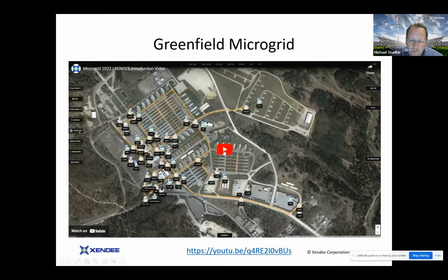This here is a real project that we did for a large campus. It's a very extended modeling approach here that we did with Xendee. It's a distributed microgrid. It has a lot of different nodes. And we had to connect all these different load pockets through cables, transformers, which we knew from the client. And then we were modeling at all these load pockets, different technology options. And the goal was actually really to figure out if we should have a more centralized PV system, or maybe the PV should go more on the roof, and how this will impact the transformers, the cables, and all this.